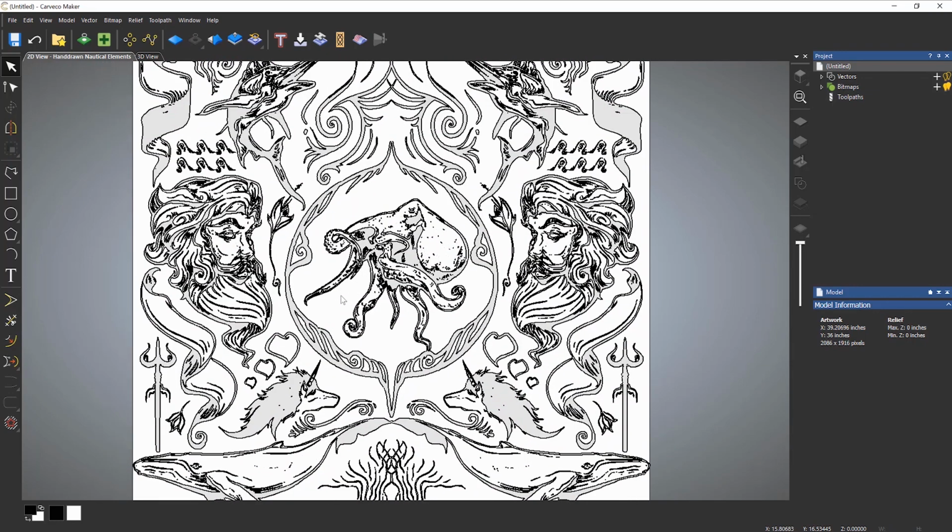Okay, so what I'm going to do now is just show you how to machine this. So at its most basic, this tutorial, I'm just going to show you how you can trace around an image and then machine it. I'm pretty sure that I will have a couple of problems with the vectors that this has generated because it's quite a complex drawing. Now the way that I can check that, the quickest way, is to just try to create a toolpath on there. So I'm just going to try to V-Bit carve this.